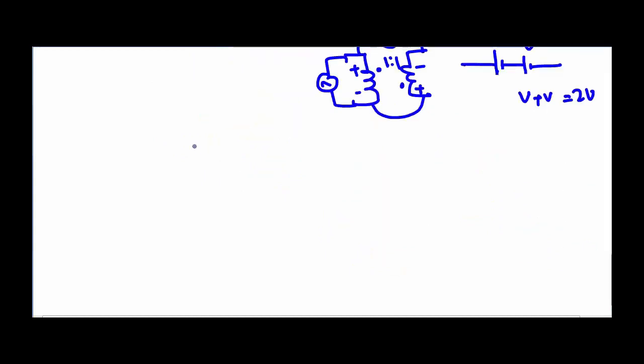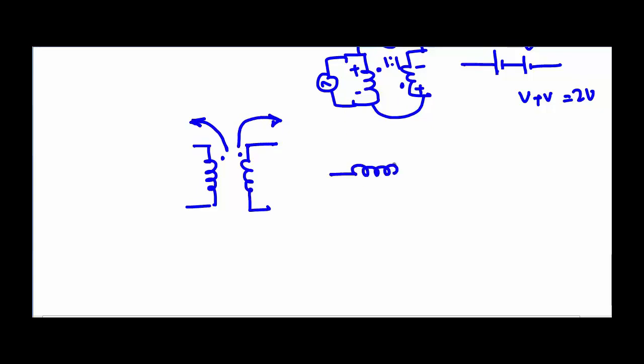So at this point itself, let me just mention one thing which we will be assuming as we proceed with our discussion regarding the connection of windings for a particular vector group. And if it is something like this, and if I'm rotating this winding by 90 degrees in this direction and this winding by 90 degrees in this direction, then it's obvious that it is going to be something like this. The dot will be located at this point, and for this one the dot will be located at this point, and if this is drawing current in this way, it is going to supply load in this way. So this is the way the current flows in the transformer if the dots are located this way.